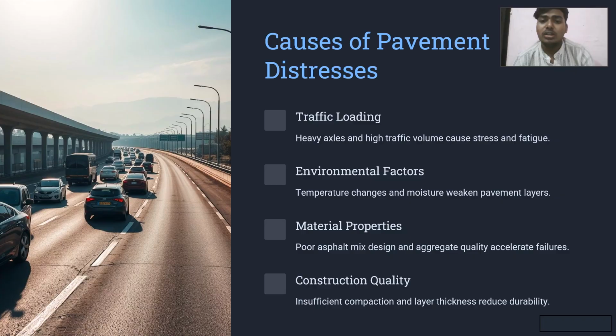Now we are talking about causes of pavement distresses. Traffic loading: heavy axles and high traffic volume cause stress and fatigue. Environmental factors: temperature changes and moisture weaken pavement layers. Material properties: poor asphalt mix design and aggregate quality lead to failure. Construction quality: poor compaction and inadequate layer thickness reduce durability.